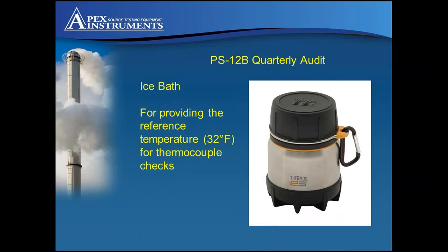The last part of the kit is an ice bath. It's a wide mouth thermos used with ice and water for verifying your thermocouples, which also includes the stack probe. You can also just use a bucket of ice, whatever's easier. That's what a lot of the stack testers I work with end up using. Good thing about this, it does not require any calibration.